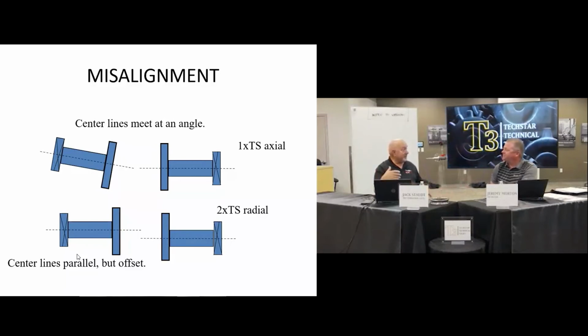So it's 15 in the winter and 105 in the summer, and vibration levels increased as the temperature increased because of thermal expansion. They thought they had an alignment issue, and they called me out to verify the relationship of the thermal expansion to when it was cold aligned. Basically, their next opportunity, they're going to do another alignment and try to do a hot alignment.